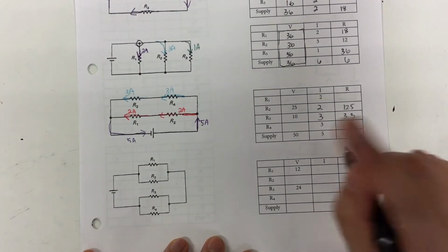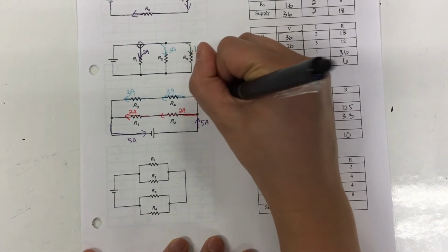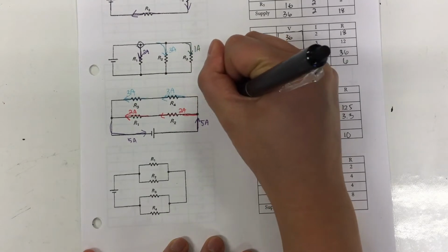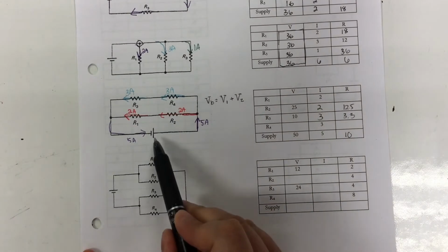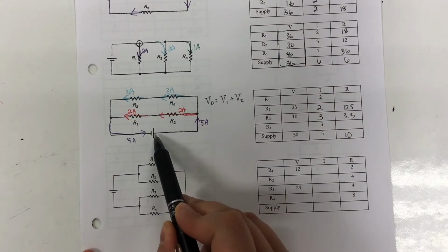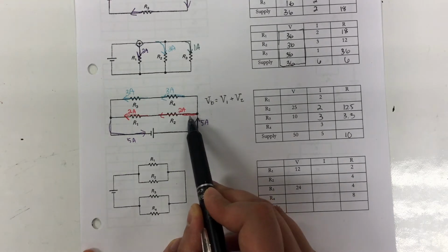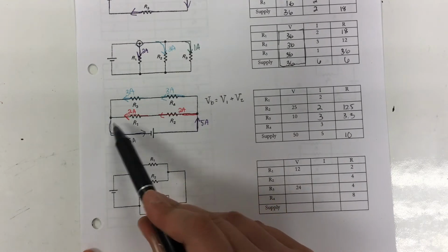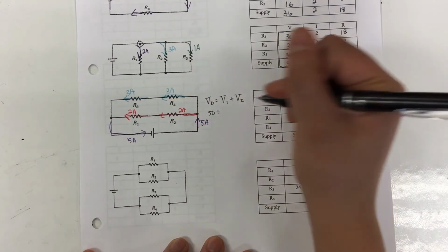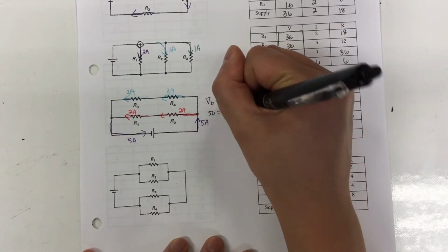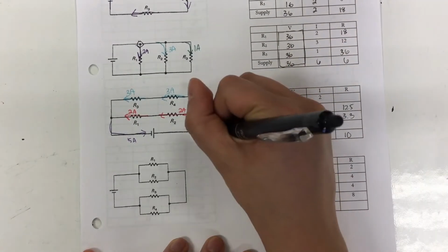Along any closed loop, the supply has to give out enough energy for an electron to make it through the obstacles it meets. So if the loop goes along path 1, 2, the conventional current goes to this junction, goes through R1, then R2. Well, the battery supplies 50 volts. It takes 25 of them to get through R2. So V1 must also be 25.